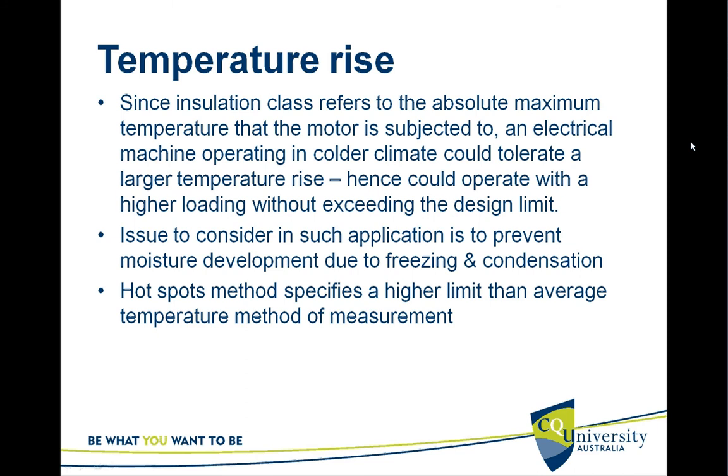An issue to consider in such applications is to prevent moisture development due to freezing and condensation, because if the normal temperatures are closer to the condensation of water vapor, then that could be a bigger problem for motors operating in such an environment, not the temperature rise.